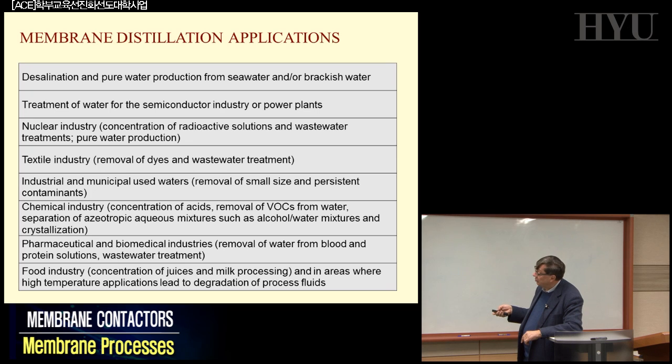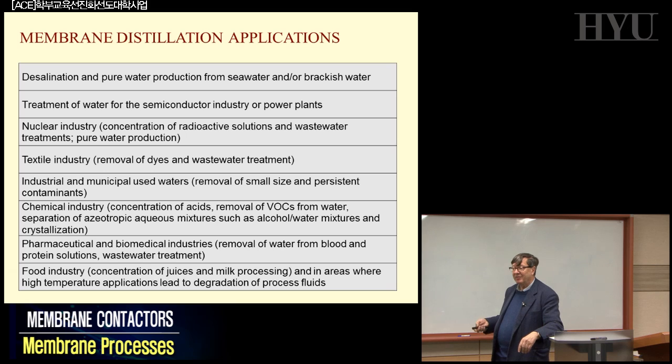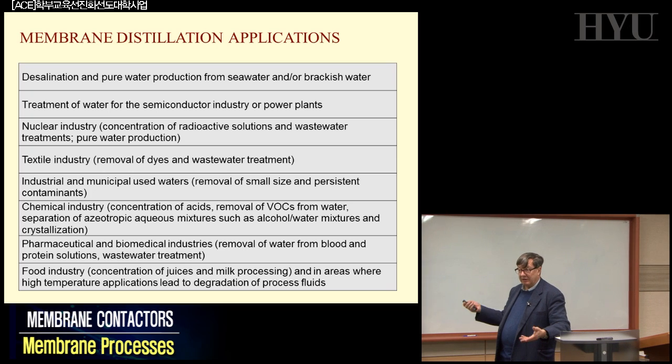Keep in mind some other applications, for example the nuclear industry. Nothing is going into the vapor phase. So if you have, for example, the problem that happened in Japan, with radioactive isotopes, very difficult to treat with normal membranes, because radioactivity, the energy, can attack the polymer. By the way, these are fluoropolymers, very resistant. But second, no ions go into the vapor phase. So cesium or cobalt, etc., can be 100% removed from the water if you utilize this kind of technology.